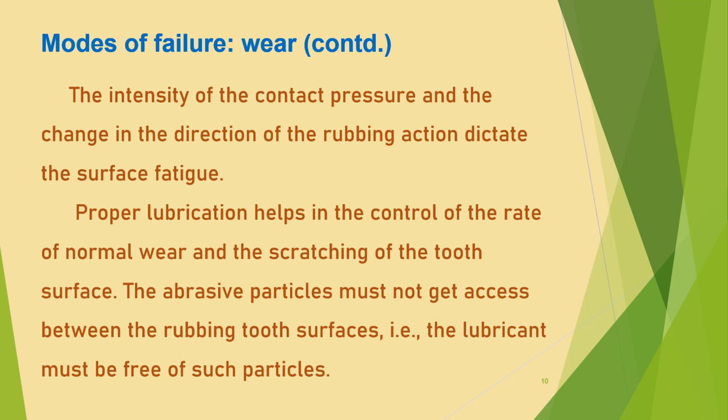The intensity of the contact pressure and the change in the direction of the rubbing action dictate the surface fatigue. Proper lubrication helps in the control of the rate of normal wear and the scratching of the tooth surface. The abrasive particles must not get access between the rubbing tooth surfaces. That is, the lubricant must be free of such particles.